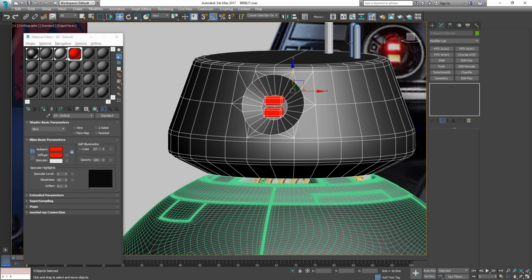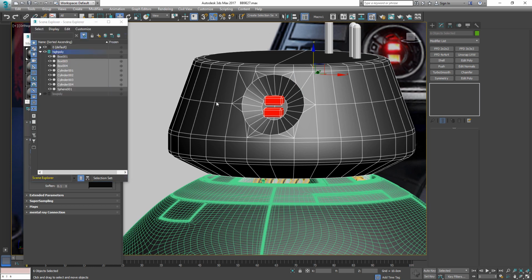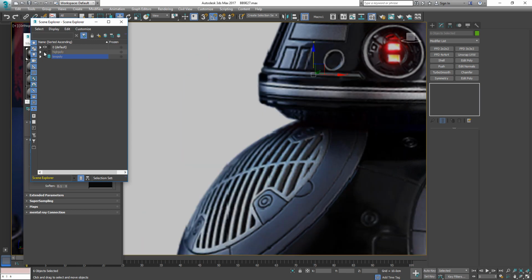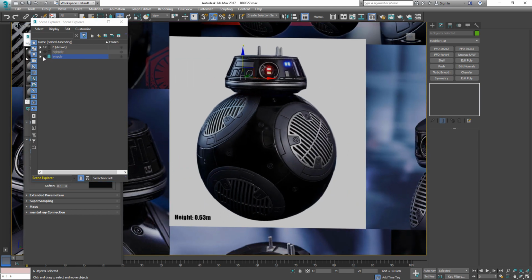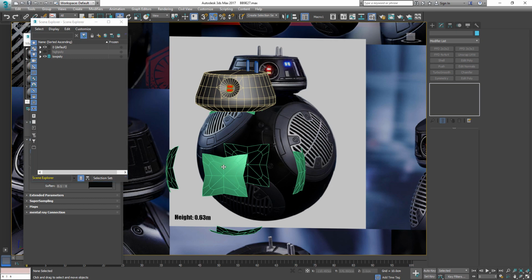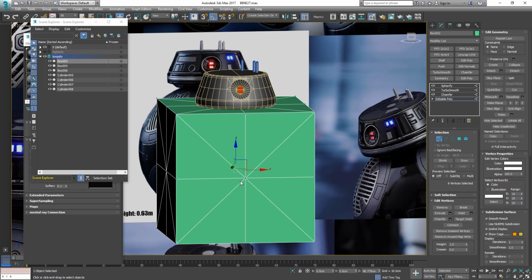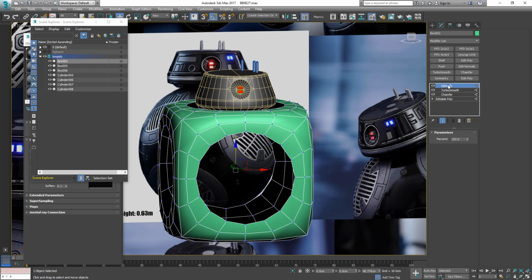And now I'm gonna select that head, the lights and the antennas, 6 objects, bring up our Scene Explorer, and now I'm gonna right click it, make a copy of everything. So with that active selection of the copied things, we make the low poly active and add it to the active layer. So now if we toggle these two, you will see that our low poly has the head in it, and something got messed up here with that part. Let me go back here. And it looks like the selection for the vertexes was not active anymore for some weird reason.